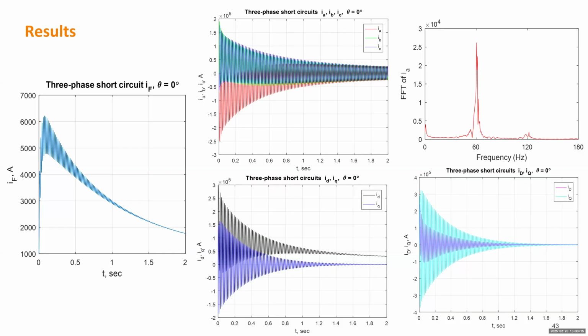And this is the damper winding currents. The damper winding currents will increase right after the fault. This one is a Fourier transform of the current. So you can tell the fundamental harmonic is still 60 Hertz, but because there's some fast dynamic, you also have some higher harmonics. I'm not going to go into detail to analyze why the waveform looks like such a plot.